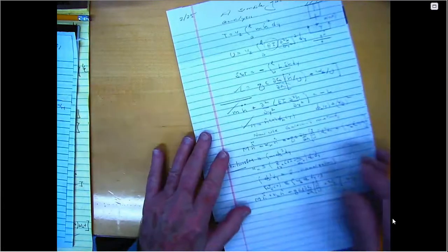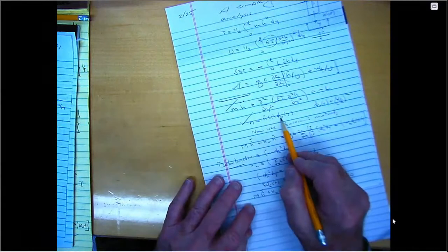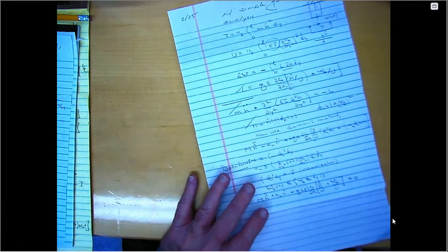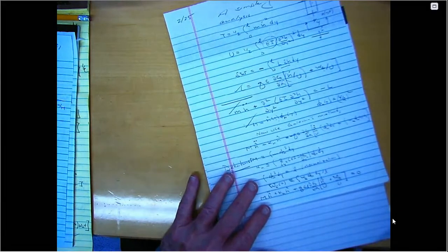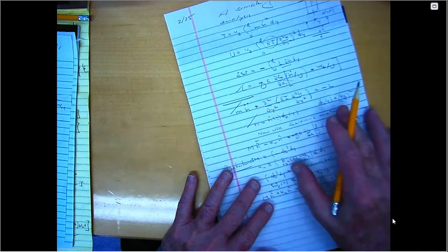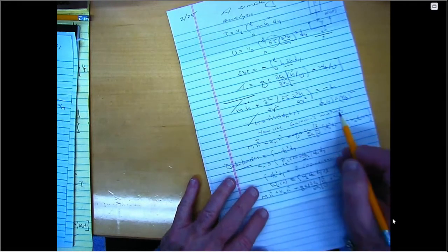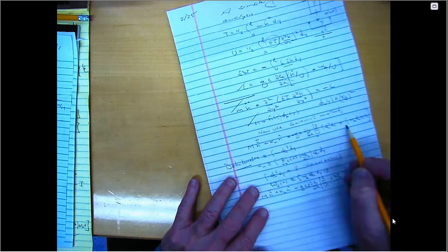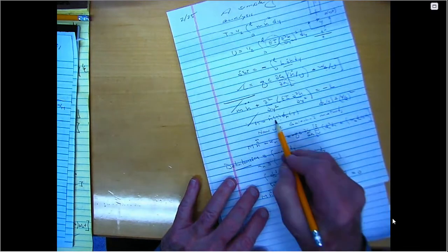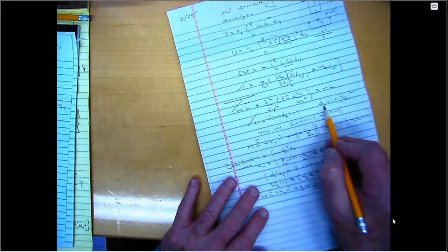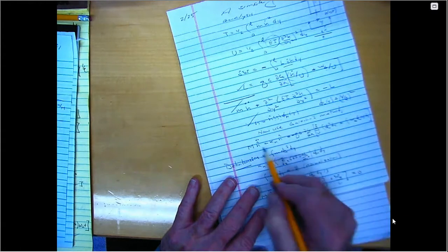All right. Now, when I take this representation, I'm only going to use one mode. But we could use 2 modes, or 3 modes, or 4 modes. So let's do one at a time. I take this and put it in here. Then I use Galerkin's method, and I can get this equation. What is Galerkin's method? I put this in here, and then I multiply by this mode shape, and I integrate from 0 to L. That gives me an equation for H hat, which always depends on time now.